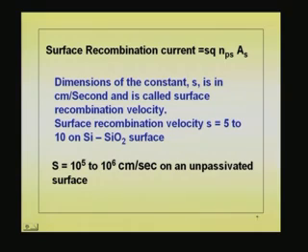Now, leaving aside that, what we are trying to point out is, in the case of silicon, that recombination velocity is very, very small, because it is passivated with silicon dioxide. So, you do not really have to worry about the recombination on the surface, and if you use the 1-dimensional equation, it gives you fairly close results to experimental results, whereas here it is far off.